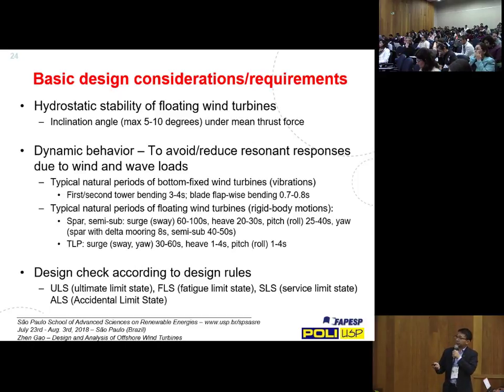And that is a static consideration. As I mentioned, thrust force is a very important source of loads on the turbine. And then you also have to consider the dynamic behavior of the turbine. If you look at the floating wind turbine, basically we look at the rigid body motion of the whole system. And then you also have vibration issues. For example, blades are very long and slender, and they can be easily bent. And the wind loads are dynamic, so you have vibration issues. We'll talk about this in detail later.